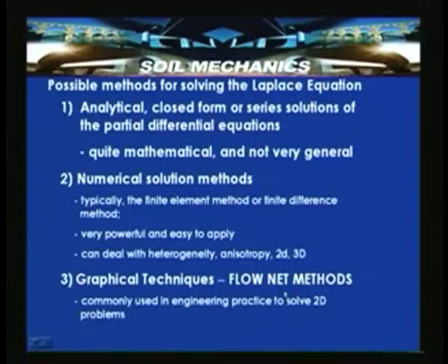So, the flow net methods can be applied for solving and computing the flow through a two dimensional plane, so that you will be able to compute the seepage or leakages occurring in dams, all these things which are applied through two dimensional flow conditions. So, if we are listing out the solutions, we have analytical and closed form series solutions of the partial differential equations, numerical solution methods, or graphical techniques based on flow net methods, which are commonly used in engineering practice to solve two dimensional flow problems of geotechnical structures.